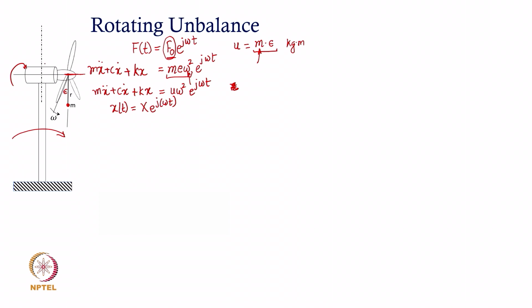In any case, this unbalanced force can either generate a vertical translatory or vertical harmonic force, or it can generate a harmonic torsional excitation, or a harmonic moment, and so on. So, whichever way you model this vibratory system, the excitation still is harmonic, and thus the process of investigation is still the same.